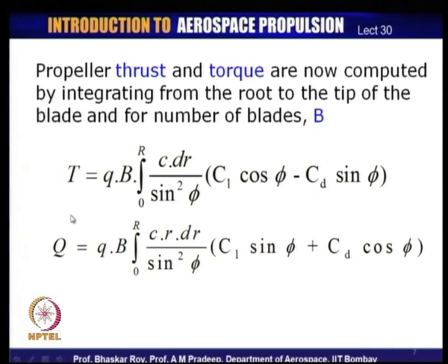So, these two are to be very accurately estimated. Only when the total torque is properly supplied do we get the thrust that is required to fly the aircraft. This is the thrust you would require to fly the aircraft in a predetermined manner. To do that, you need to be supplied with that kind of torque from the engine, and of course, the propeller power needs to be matched with the engine power. So, these are the parameters that you finally require for the propeller to create thrust, based on the aircraft on which it is mounted and the engine to which it is attached.